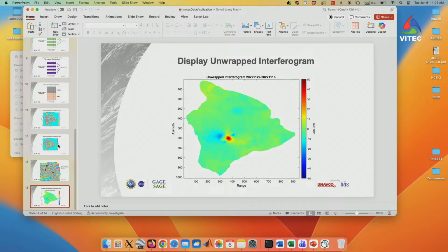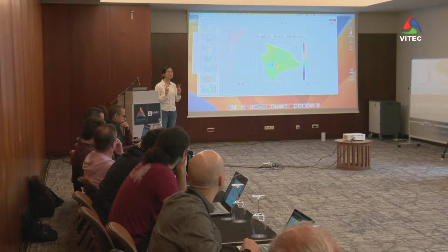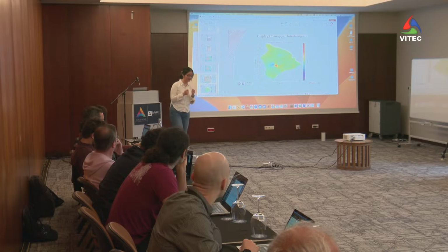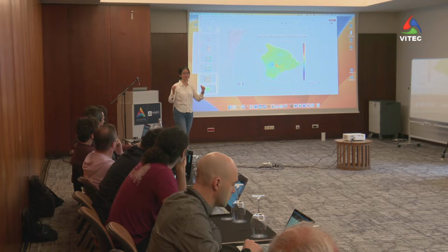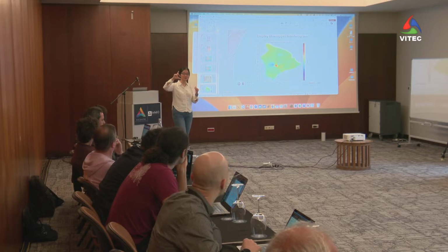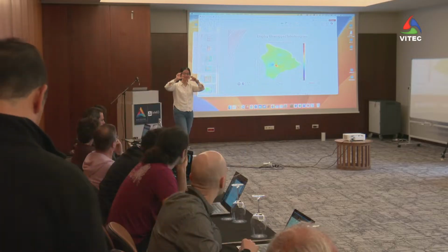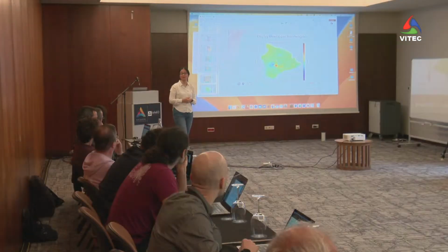For the read, we have two routines for reading the DEM data and the amplitude data. And for plotting, we have routines that visualize the amplitude image from the complex data, and the phase. There are two tricks for the plotting, and you can probably modify them a little bit. For plotting, the radar amplitude data has a very large range, so things that are bright and things that are dark can differ by several orders of magnitude. That's why we clip the data range to exclude the extremely bright and the extremely dark values, and then scale them when we display the PNG image.